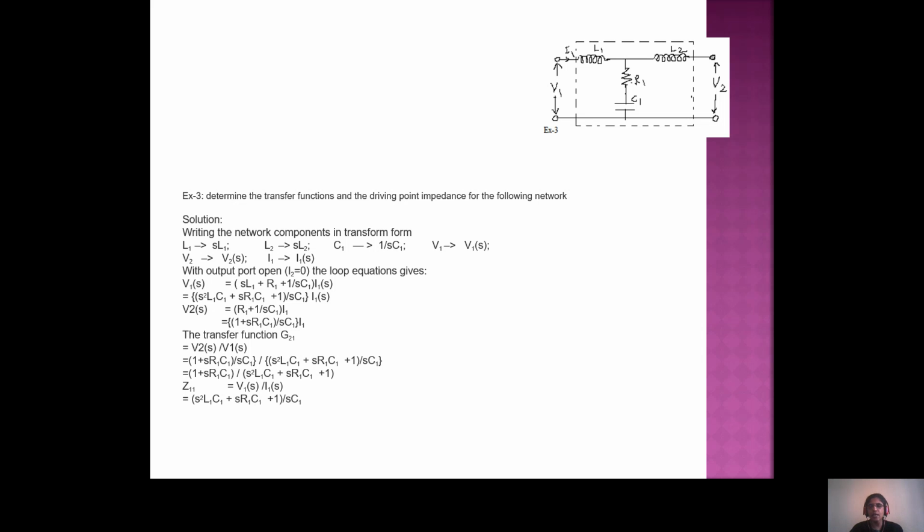So in this unit we discussed the two-port parameters and two-port functions. Under the functions we discussed the network functions, depending upon the driving point functions and transfer functions. Driving point means the parameters are related to the same port, and then it is called driving point impedance or driving point admittance. Transfer impedance and transfer admittance relate the voltage of the first port and the current of the second port. So this is about the topic of network functions.